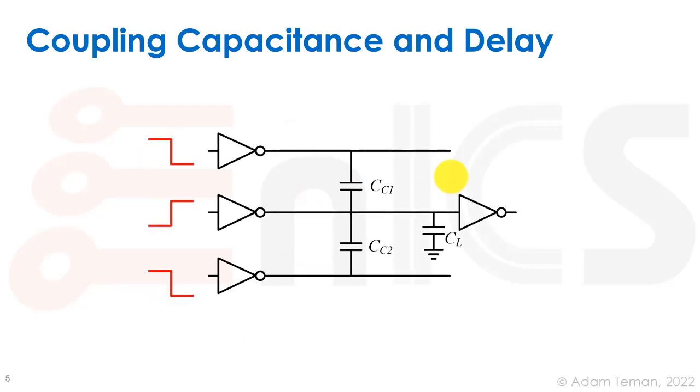So in this case, again, we have this toggle where the middle inverter is going to toggle separately from the other two inverters, causing a different type of voltage swing. So if at the beginning over here we had VDD over here and 0 over here and 0 over here, that means we had a voltage swing of VDD in this direction. We could call it a minus VDD over here. And again, the same thing over here, we had this minus VDD over here. On the other hand, after our swing, we had 0 over here, VDD over here, and VDD over here, causing us to have a plus VDD this way,